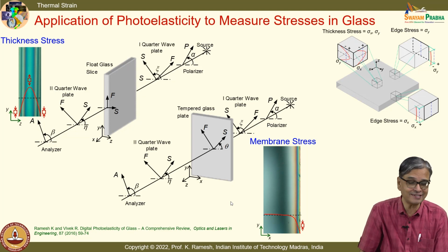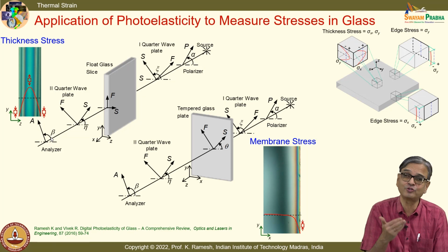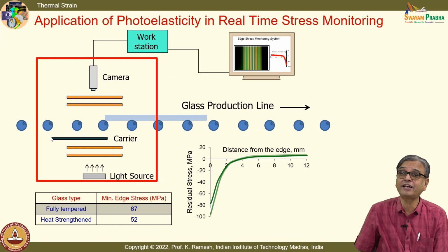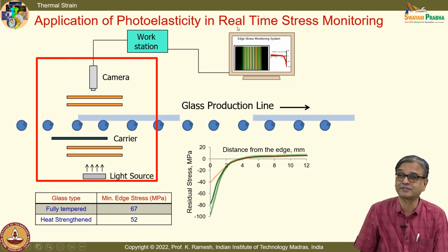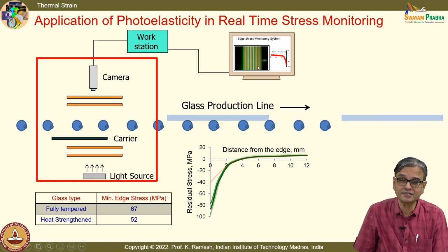And you find glass is a green material, and people want to understand glass and also manufacture it properly. So, I should know how to measure it, and I should also monitor it while I manufacture. I can have an online system where I look at the digital image and have software to evaluate the edge stress developed.